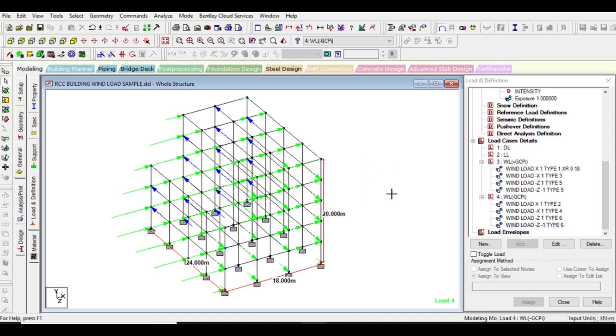So this was just a short exercise to make you familiar with how we can calculate the wind loads as per the American standards. What are the various codal guidelines which guide us on how to calculate the wind load for main wind force resisting systems, that is MWFRS, and what are the values for various types of openings, that is partially enclosed, enclosed and open structures, and how we need to take the values for plus GCPI and minus GCPI as per the codal guidelines.